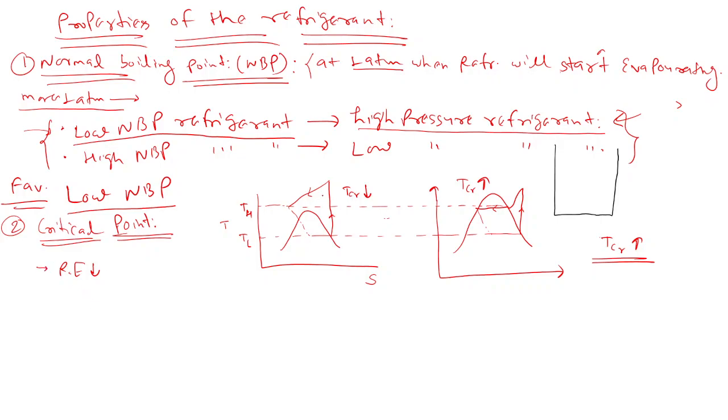Okay. Here is what happens. Let's suppose it comes out from here and goes to the condenser, and due to this latent cooling, it comes here. It is liquid. For liquid, its enthalpy is less. So in the throttling valve, it is an isenthalpic process. If it is very less, then it will come here. Then this part is high because this enthalpy is less.